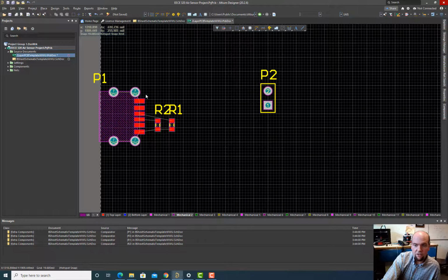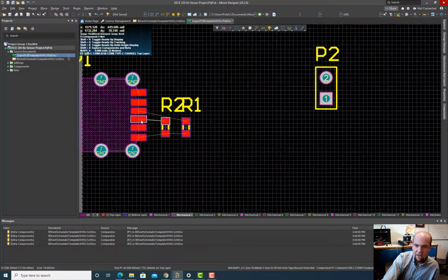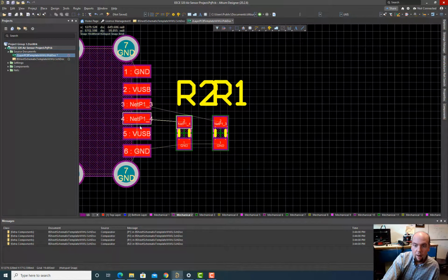All of these parts, we have a representation right now in 2D, which is showing the signals. This red is showing copper that's on the top of the board. So it's this top layer copper. Blue would show copper on the bottom layer of the board. The boards that we use are going to be 2-layer boards. If you go fancier, you can have 4-layer boards, 6-layer boards, 10-layer boards. iPhones, I think, now are 12-layer boards. If you're working in military applications, sometimes you'll have 20-layer boards. You know, they get crazy.